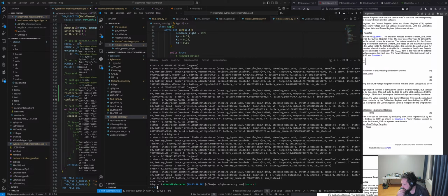Well, the camera is pretty active when it's doing that find cone task, because it's running a YOLO v7 based object classifier, and it's also running a video encode. It captures the video, encodes the output, and also then downsamples that image and feeds it into a YOLO v7 model.